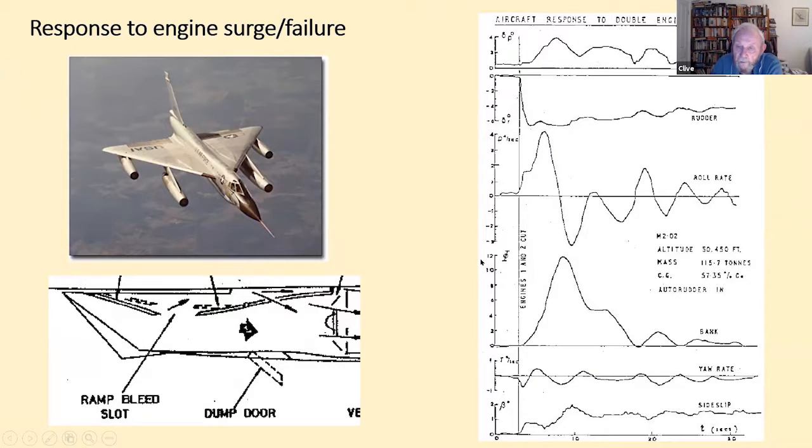The reason it comes about that way is because of this feature of the power plant. If the engine fails, all the flows are going there, and instead of rushing out and unstarting the intake, some of it goes down there, but most of it is expelled through the dump door, which is automatically opened when the pressure inside here builds up.